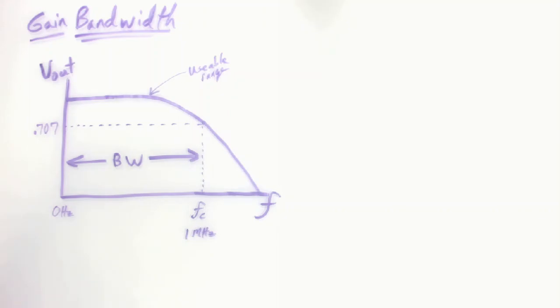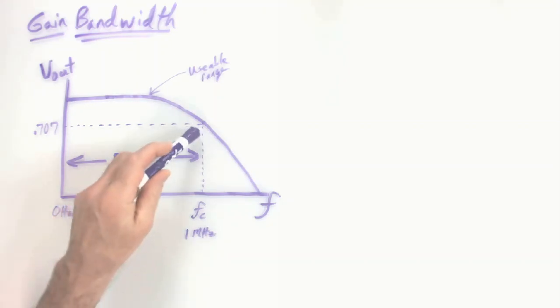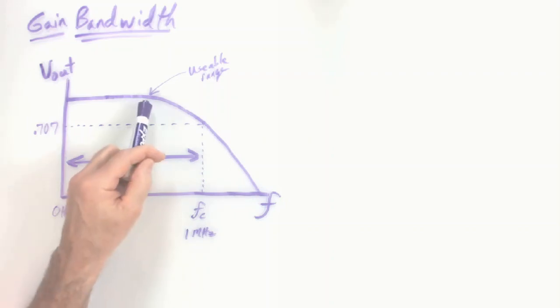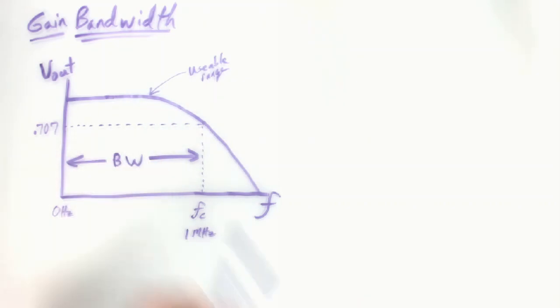So always know that. Keep that in mind when you're speccing out systems or things that have a bandwidth rating. I always have to remind myself of that. That doesn't mean you're good to go. You're good to go for frequency measurements up to 1 megahertz with a 1 megahertz bandwidth scope. And if you don't care about the specifics of the amplitude, that's fine. However, if you're trying to get an accurate amplitude measurement, you're going to only have a usable range somewhere in this vicinity.